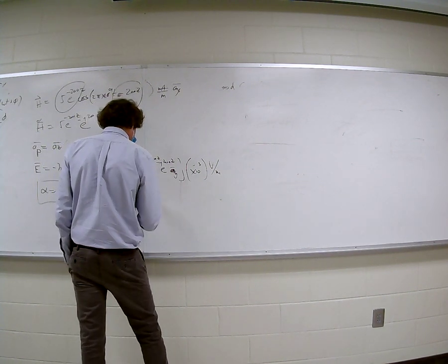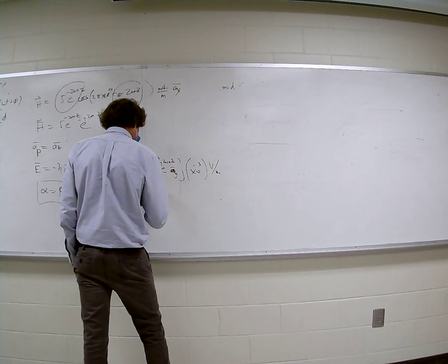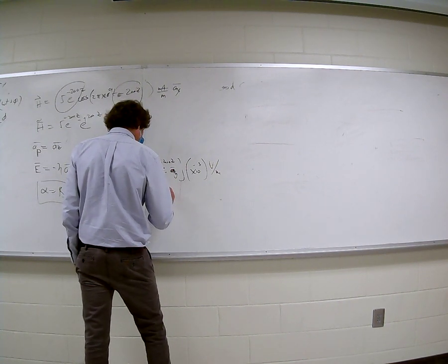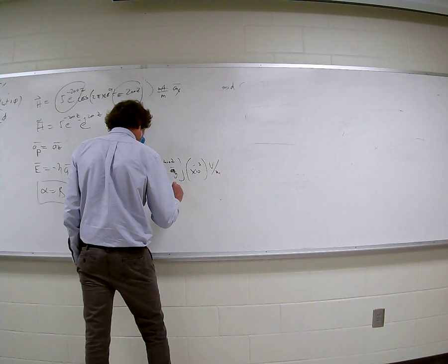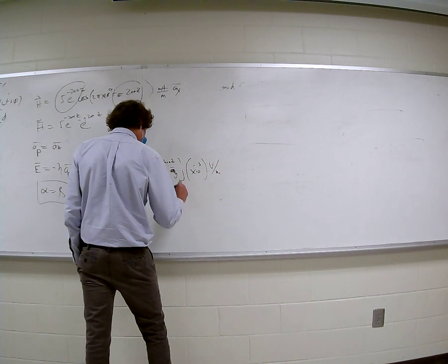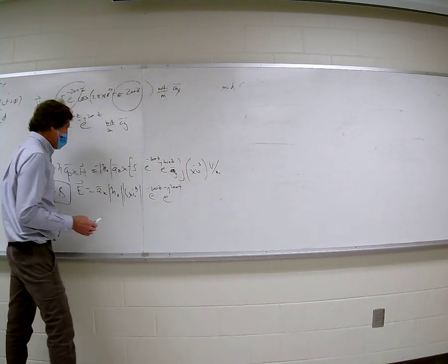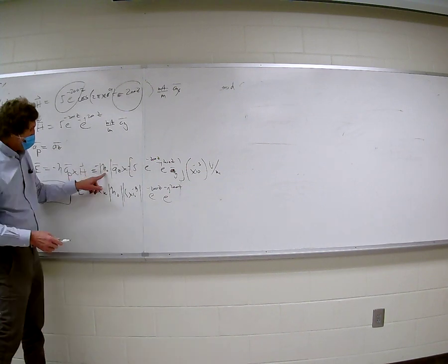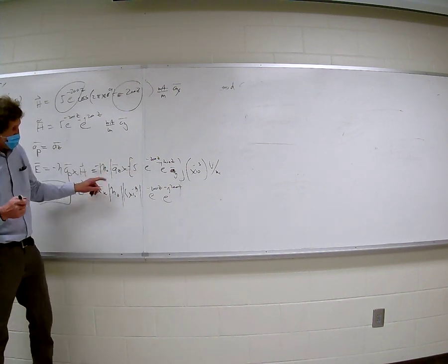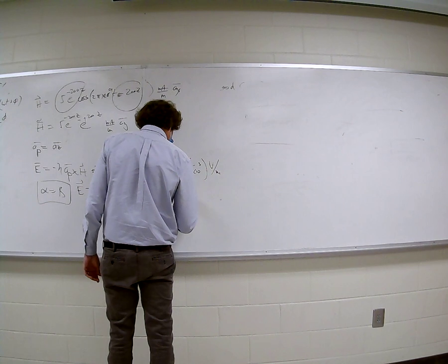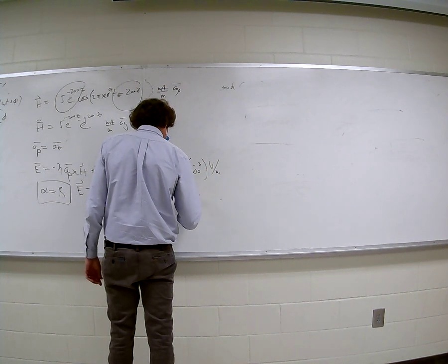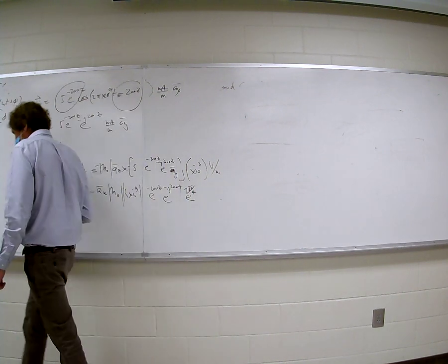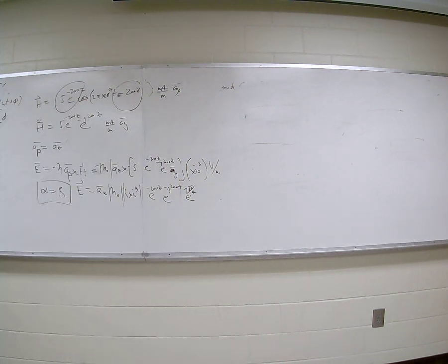And then it's going to be e to the minus 200z, e to the minus j 200z. But this phase angle here, it's really eta naught, and the phase angle is 45 degrees, so it would be times either e to the j pi over 4 radians or e to the j 45 degrees, either one. You have to include the phase angle. You with me on this?